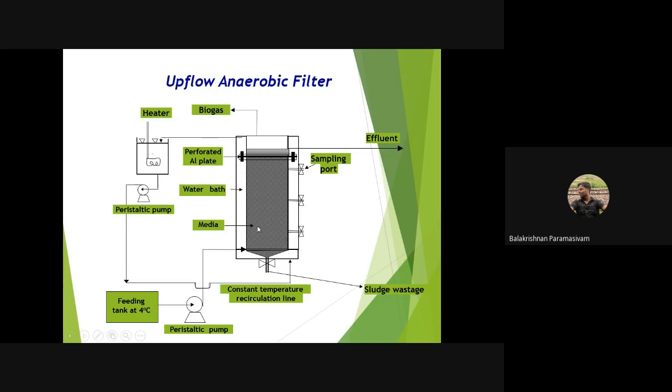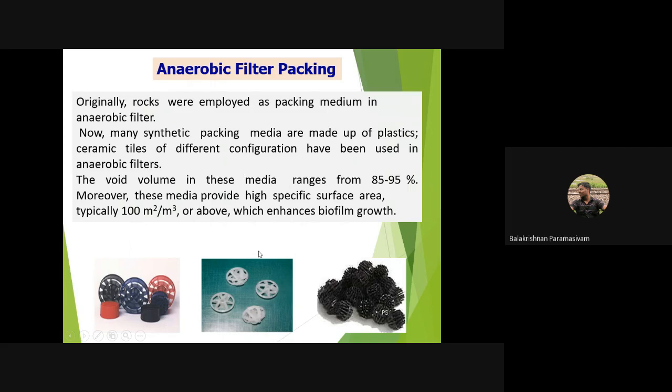So the media, we will be filling the media. Water will go to the bottom of the tank and it will come to the top of the tank. The treated effluent will come from this point and we will get the biogas. This biogas can be used for domestic purposes. In this case, these are some kinds of filter media.